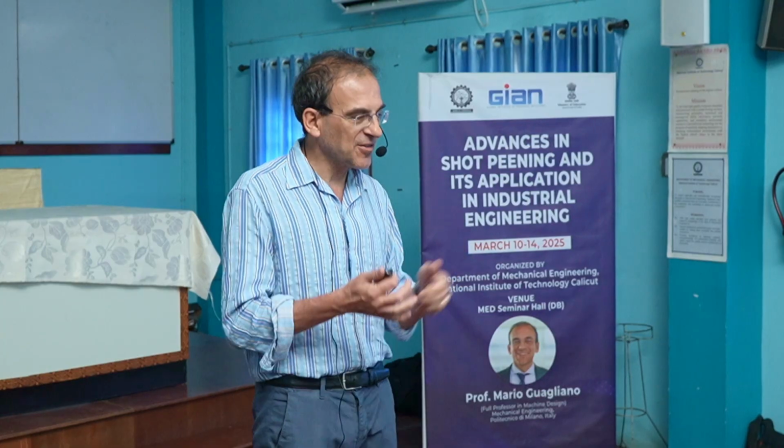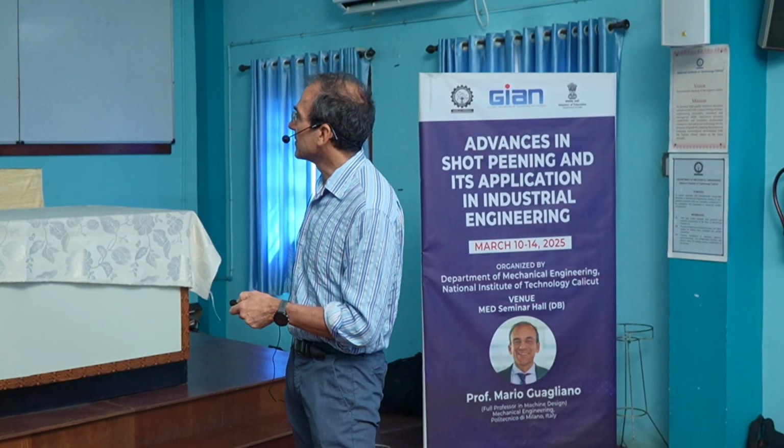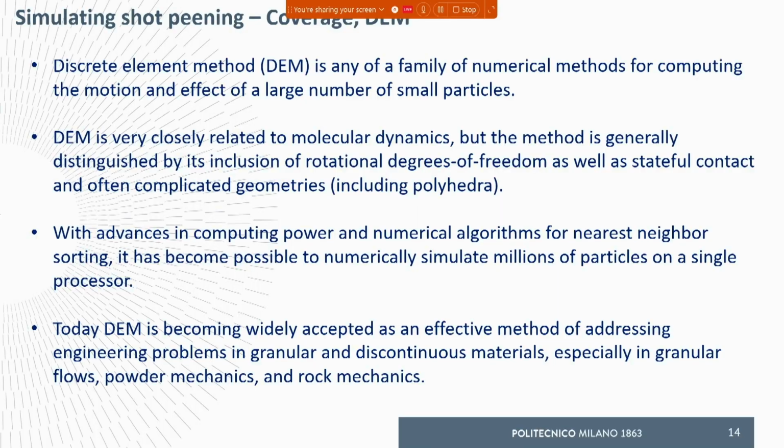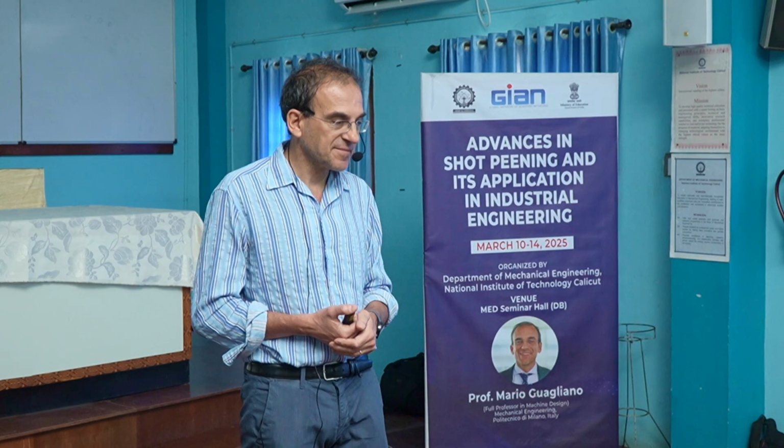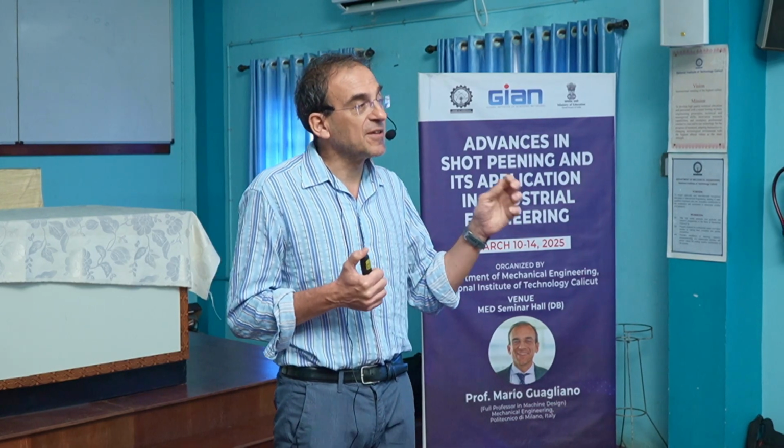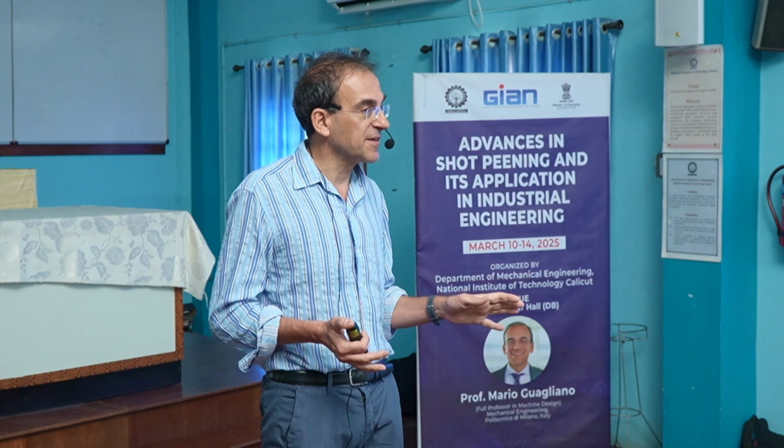Let's say, just to introduce the method. It's close to molecular dynamics, but the method is generally distinguished by its inclusion of rotational degrees of freedom. Okay, so we are able to include the rotational degrees of freedom as well as often complicated geometry. The DEM is not considering plastic deformation.